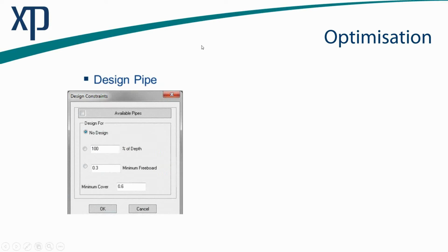For pipes, we then need to assess your rising mains. We need to assess our gravity mains. We can design for full flow, or 50% flow for dry weather if that's a requirement from your guidelines or regulations. In a high flow event, we may wish to obtain a freeboard, possibly below the lid of your manholes across your network, to ensure that you don't have surcharges onto your open environments or your overland flow paths or natural creeks and rivers.